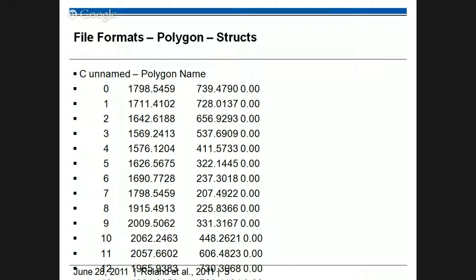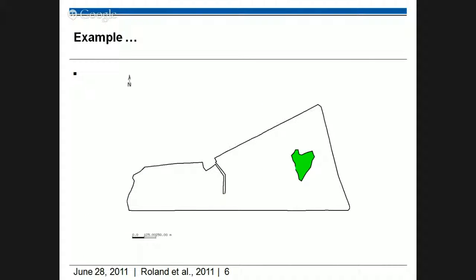As its name says, Polymesh works with polygons to define pretty much everything, and they look like that. You have some comment line, in which you can put the name of the polygon if you want, and then the list of the points of the polygon with, again, X, Y, and Z. This is the case with units in meters. You can do it in latitude and longitude. And for some things, you don't need to specify the depths. For example, for the shoreline, you can just put 0 if you want. The file contains polygons like that, and each polygon finishes with a -1 line. And that's it.